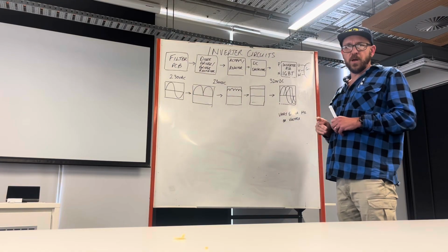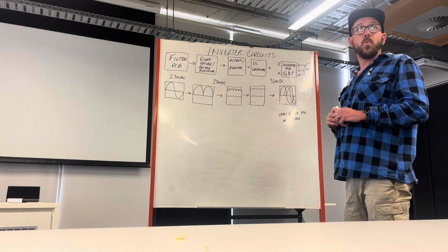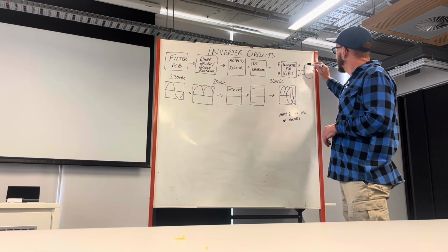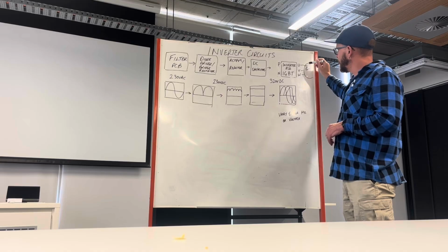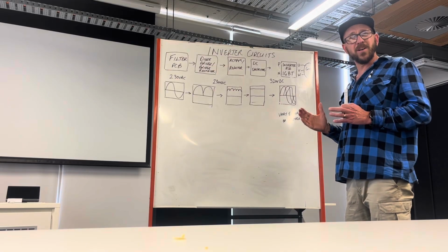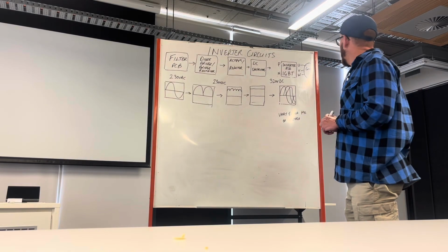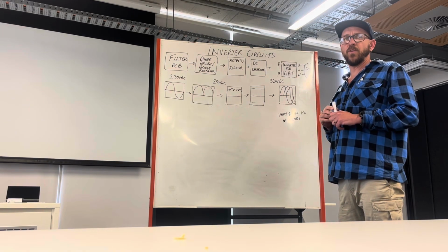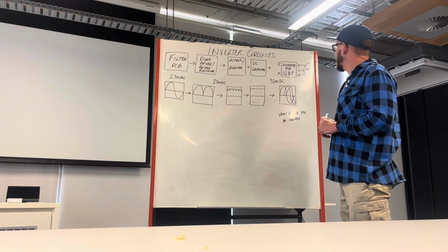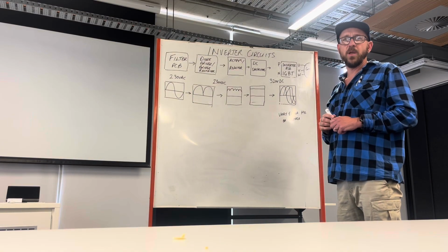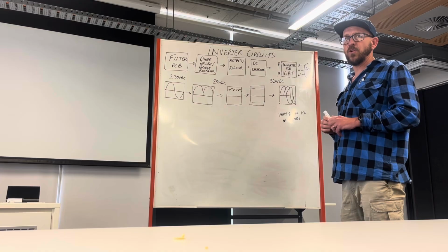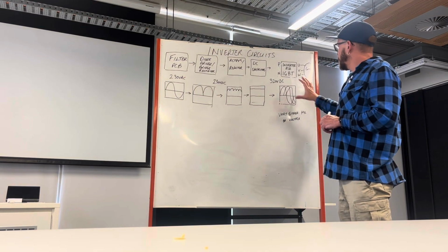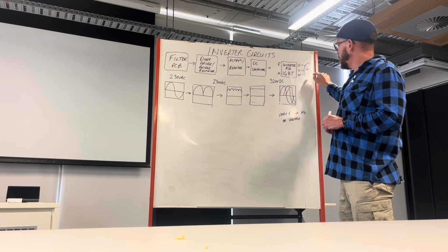The inverter compressors have ultra low winding resistance. They're wired in star, so we can test if we've got it disconnected between U, V and W. Very low resistance, down as low as 0.2 of an ohm, often between 0.5 and 0.2 of an ohm per phase. So that is a normal reading. We can also use our mega to make sure it's not down to earth, or our insulation resistance tester. So that's what we've got going on through the DC circuitry.